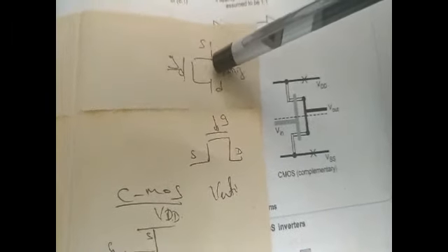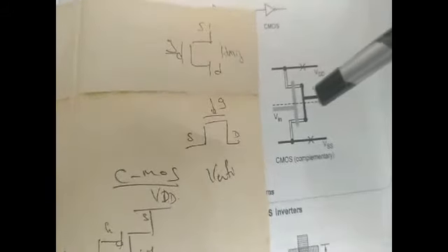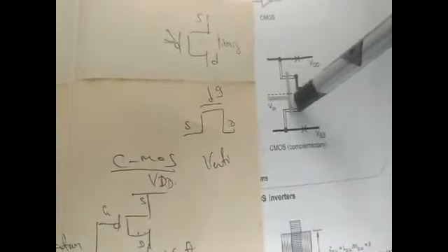Now, if you want to draw the horizontal schematic, depending upon the gate region, if the gate region is placed horizontally, then it is known as the horizontal schematic diagram. The same diagram of a PFET, if I turn it, then the gate region is placed above. So this one is representing the vertical. So this one is known as your vertical. Whatever the stick diagram has been drawn, we'll now go through the vertical schematic of an inverter and then compare it with your stick diagram.